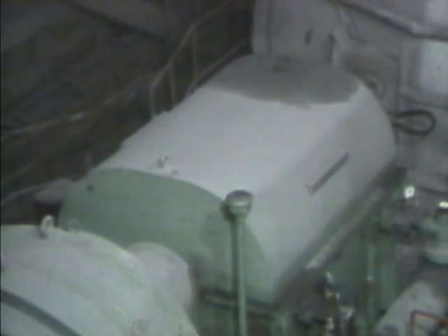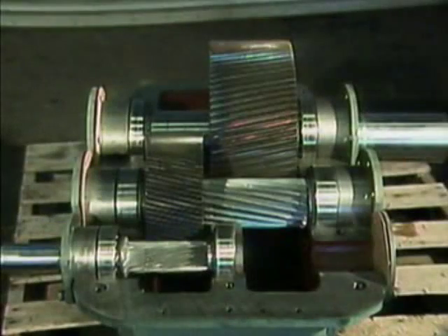When a fixed coupling is used, the speed of the compressor can be changed by changing the speed of the driver. With a variable speed coupling, the driver can be operated at a constant speed, and the speed of the compressor can be changed using the coupling. A gear drive is another device that can be used to allow a compressor to rotate at a faster or slower speed than the compressor's driver.